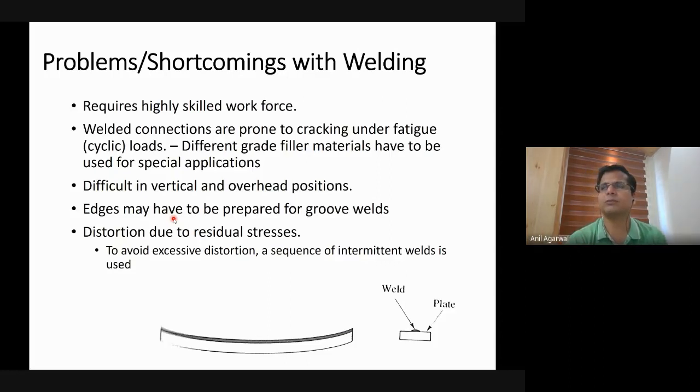So when you weld them together, you introduce a lot of residual stresses, and the concept is the same. The residual stresses arise in welded connections just in the same way that they arise in the hot rolled sections. However, these residual stresses in welded connections are much more concentrated and can lead to distortions. So if you are going for a symmetric type of welded built up section, then the distortions will not be visible, but they will be locked inside the member as residual stresses.